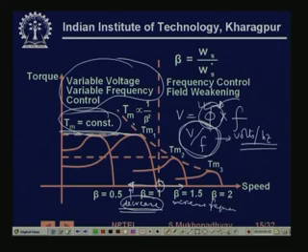Now in the DC machine, the flux automatically remains constant because it is in quadrature if you neglect armature reaction. That is why the DC motor control is simple, because you do not have to bother about the flux level, but here you have to.